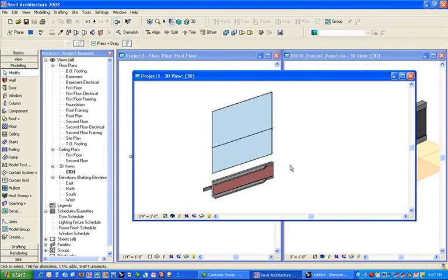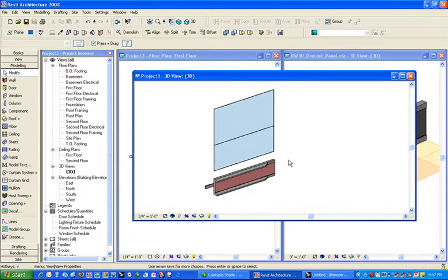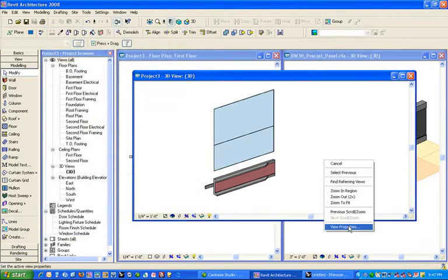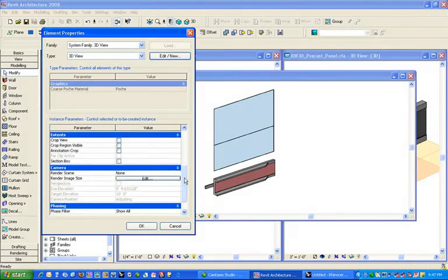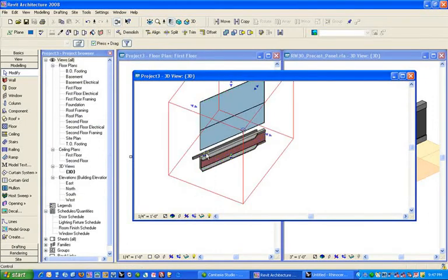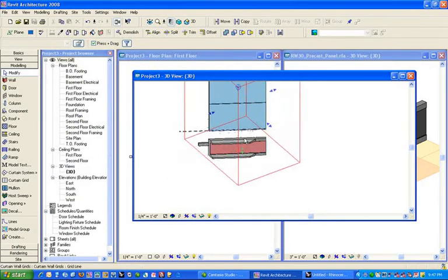In Revit you also have what's called a section box. It's a way to quickly crop an object in 3D. It's great for making drawings. You can put it on sheets, you can do lots of different things with it. And you bring it up in your viewport properties, which is either VP or right click view properties. And we're going to want to turn on our section box. So now we have this box that we can pull and start to chop up our models.